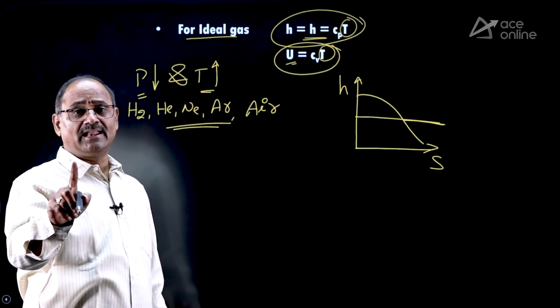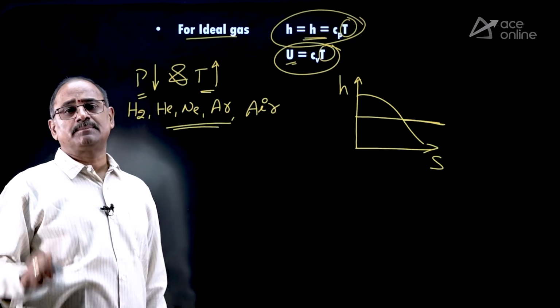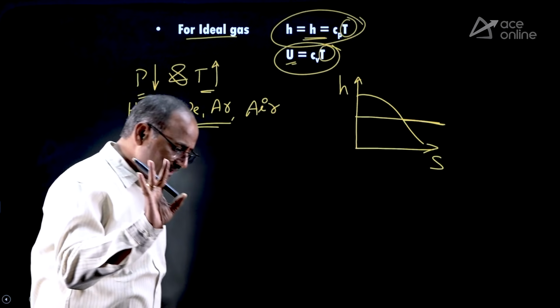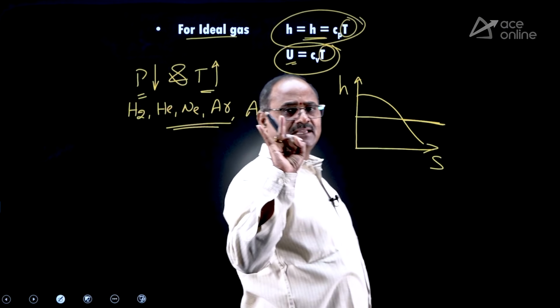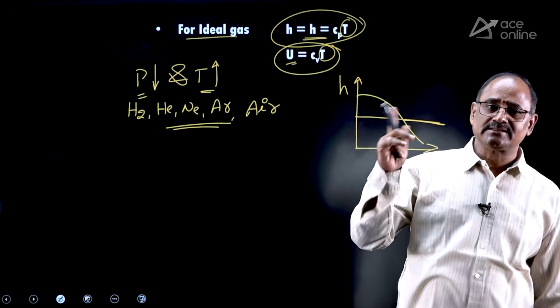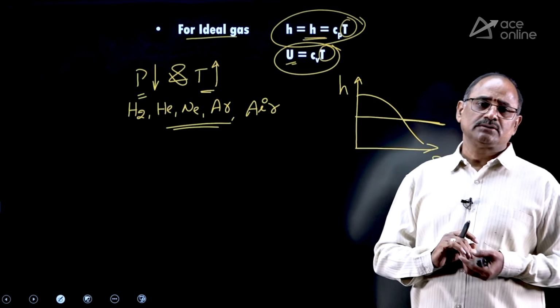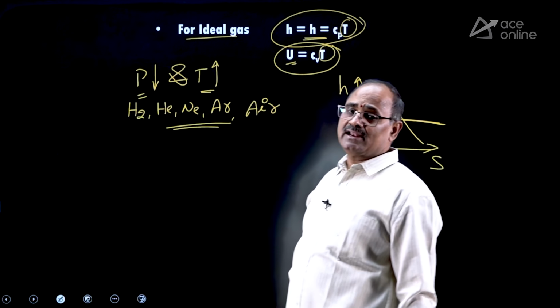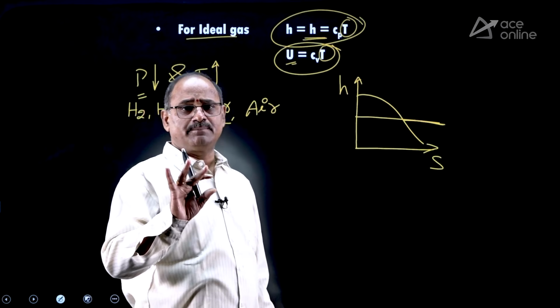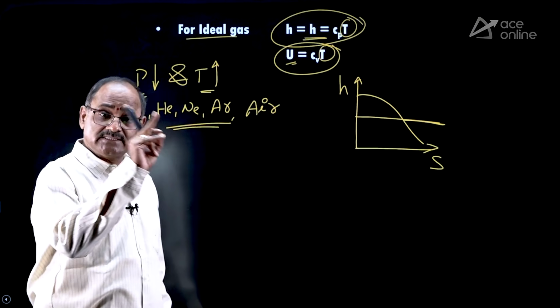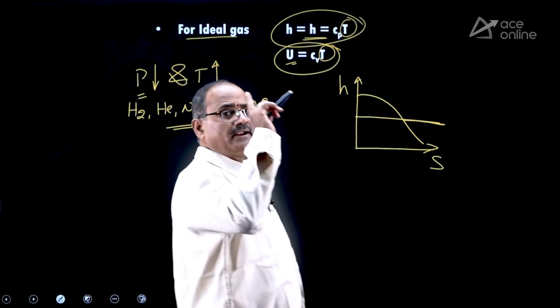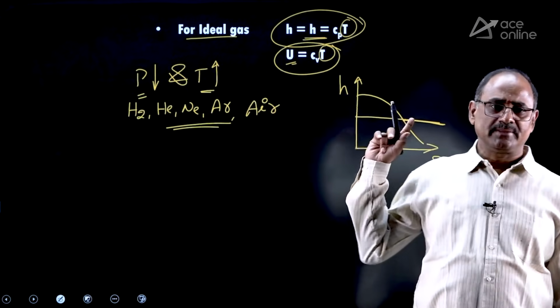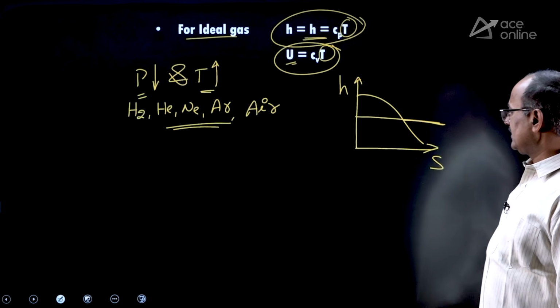We are speaking about ideal gas. In the GATE, there is no concept of real gas, right? Anyhow, for ideal gas, Cp remains same, Cv remains same, and the ideal gas are maintaining zero cohesive force. That's the reason we have concluded volume occupied by ideal gas is more than that of real gas at the same pressure and temperature. Similarly, at the same volume and temperature, pressure maintained by the ideal gas is more than that of the real gas. That point already we have clearly discussed.